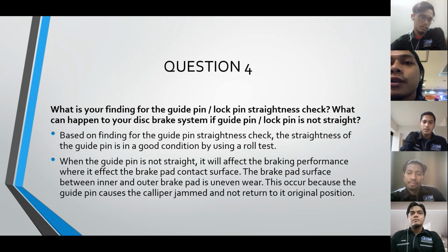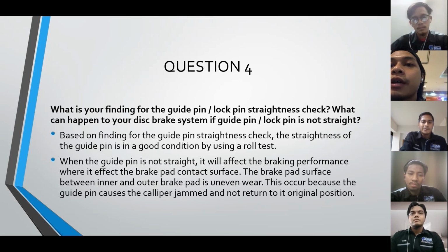For question 4, what is your finding for the guide pin, lock pin straightness check? What can happen to your disc brake system if the guide pin or lock pin is not straight? Based on my finding for this guide pin straightness check, the straightness of the guide pin is in good condition, by using a roll test.